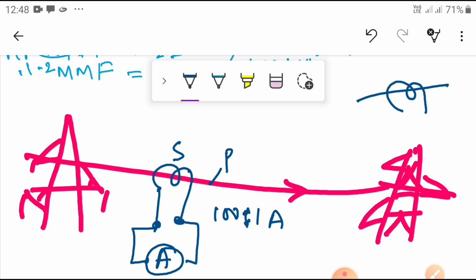We know that in a CT the primary current is dependent on the load current or line current. As the CT is connected in series with the line, the current in the line depends upon how much load is connected at the end. The primary current of the CT, assuming a constant line current of 100 amperes, is constant irrespective of whether the secondary of the CT is connected with a burden or not.